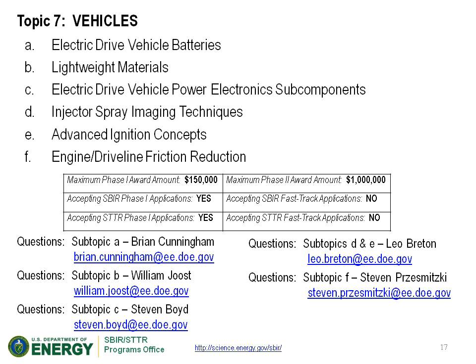So what we're looking for is advanced lubricants or lubricant technologies. Could be additives, nano additives, some other modifications that will improve fuel efficiency by reducing the mechanical friction. The one thing we're not looking for is somebody that just says, I'm going to make the lubricant thinner, unless they have a way to handle increased wear, which is where some of the additives or base oil formulations will come in. And that's all I have. Oh, and by the way, that could be for the engine, the manual transmission, not automatics. We're not going to look at automatics, and the axles. And it could be light duty, heavy duty, or medium duty.